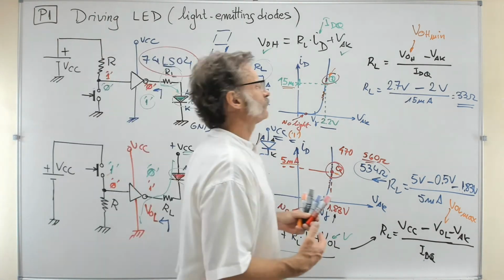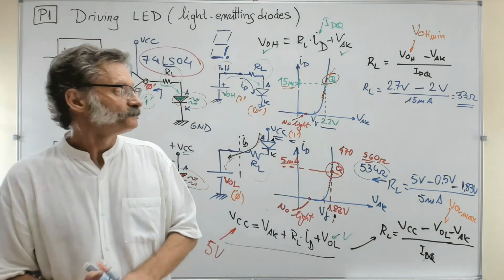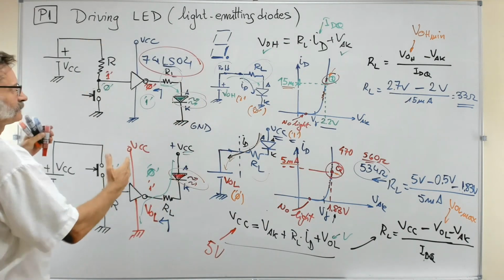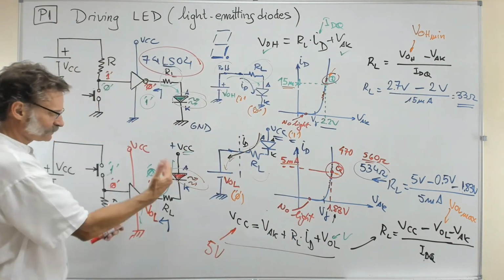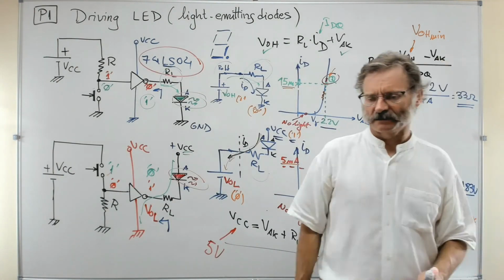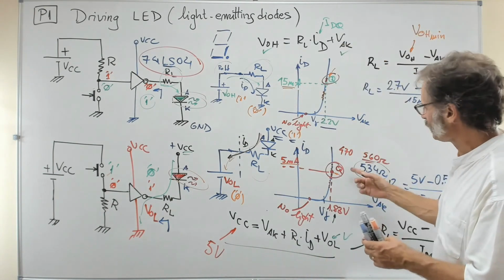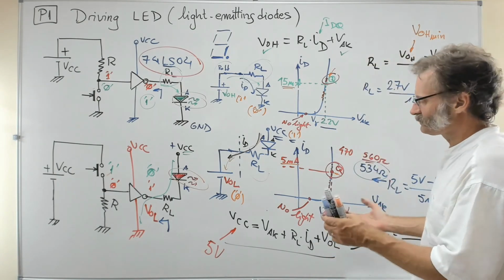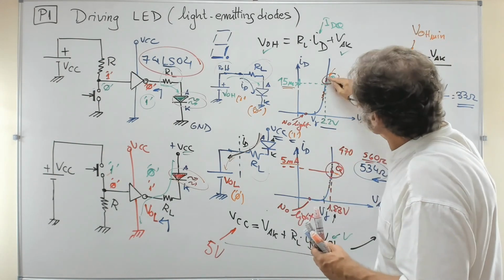So that is the way to solve this kind of circuit, guys. More or less, can you understand what is going on here? Given the circuit, you have to see which kind of equivalent you have. Depending on the circuit, you have a different situation. Then you go through the equation, and in the end you get some values. And perhaps you have to normalize them, because there is no need to use exact resistors here. You can pick the approximate one; it doesn't have to be perfect, because what you are doing here is lighting an LED a little bit more or a little less.